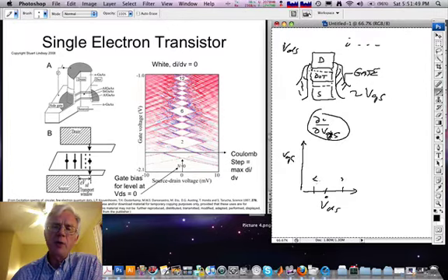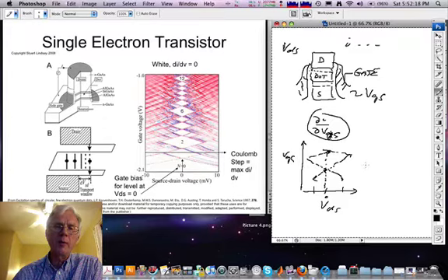However, if in a Coulomb blockade state you change the gate source voltage so as to sweep one of these states through the drain Fermi energy, then you will get an increase in conductance even at 0 bias, and that applies going the other way too, and that's the origin of these diamond-like structures. So at each point in the middle here, one state has swept through the drain Fermi energy. These points at the edge here correspond to the maximum value of Coulomb blockade.